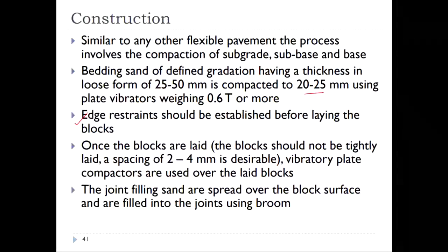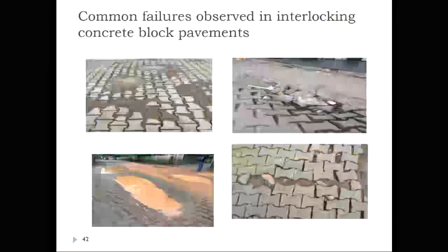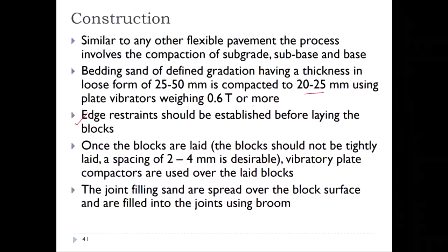You spread the jointing sand and fill the joints with brooms, so it would be difficult if you keep these blocks very tight. Once these interlocking blocks are placed, you would use vibratory roller passes in order to firmly place the blocks in the bedding sand.